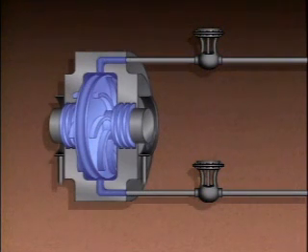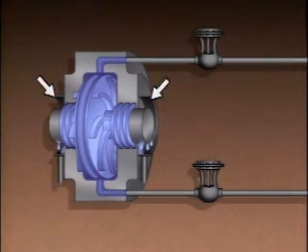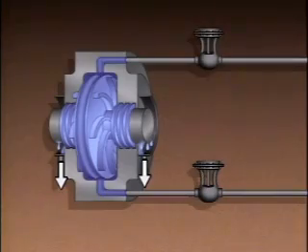This design allows some water to leak out of the seal. For this reason, shrouding is placed around the turbine shaft on each side of the seal. Water collects in the shrouding and is drained off by connecting drain pipes. As with all turbine systems, sealing systems should be regularly checked to make sure they're functioning properly.